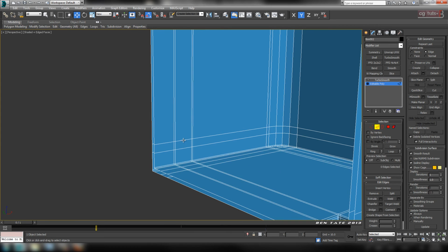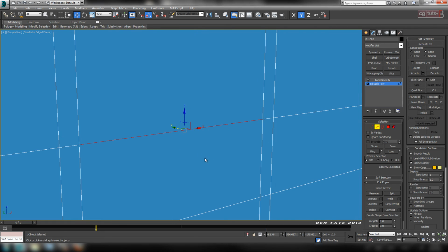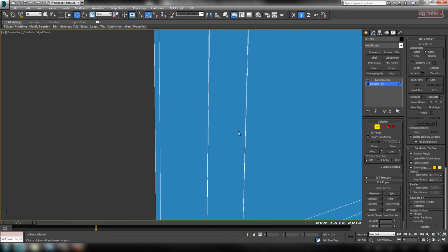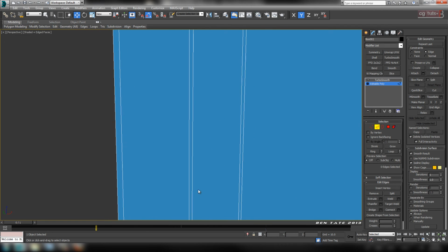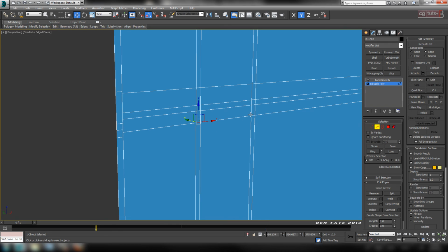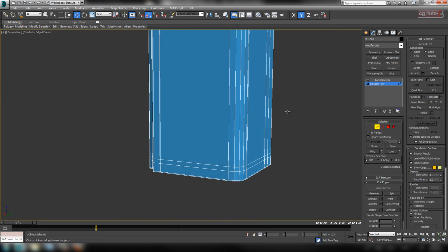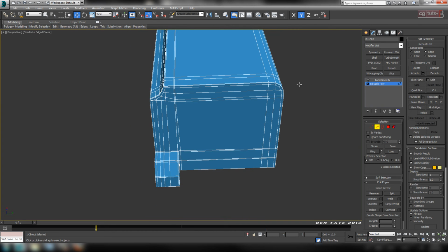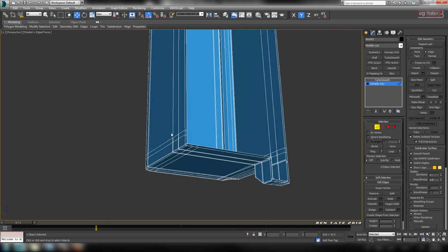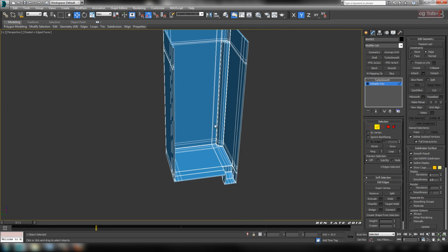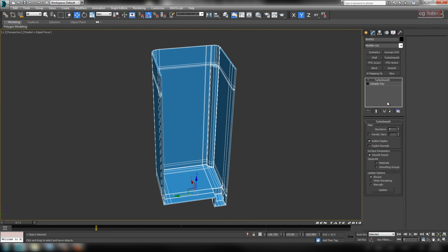And if you're having trouble rotating around zooming in, just select an edge or a vert and hit Z. Okay, that'll center the rotation to it. Okay, so grab the same two edges on the inside and collapse. And let's go up a little higher here until we find the next segment, here and here. Ring those and collapse them out. Okay, later on we can probably get rid of a few of these other loops here to clean it up. But for right now, let's maybe delete the turbo smooth.